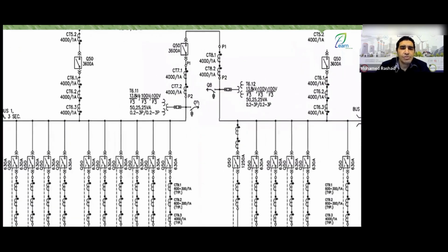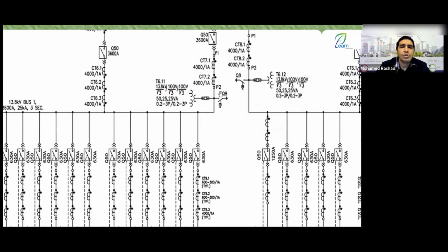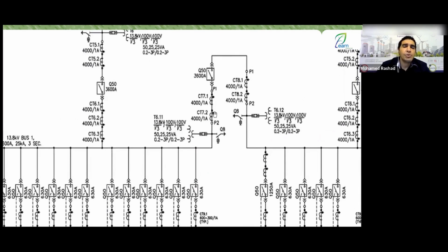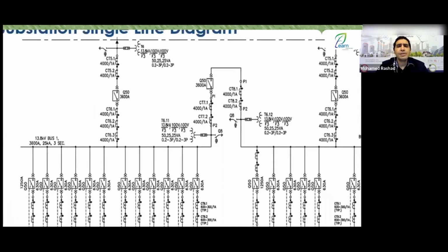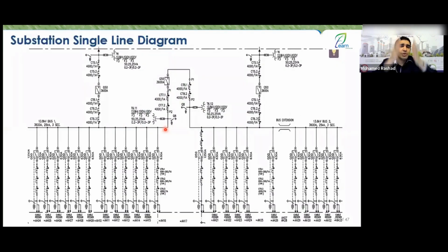Correct. So the grounding of the bus bar, where do you place this grounding? You have two directions, one here towards the bus riser and the other here towards what? Towards the output of the bus section. Exactly. Place it in the output of the bus section, meaning the bus section cell itself. In the output towards the bus riser, in a cell like that, and on the other side, place it there. How can you place it there? You can place it through a feeder or the cell we all mentioned, the bus measurement, which is where you place the grounding. So, of course, this requires me to go into the details of the cells to tell you exactly where the grounding is located.